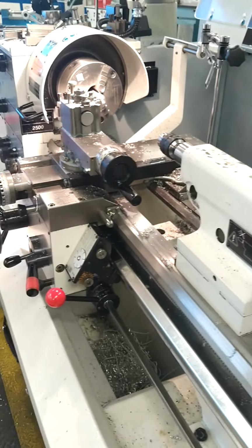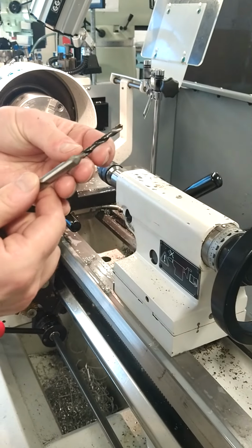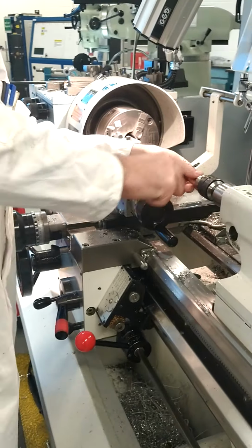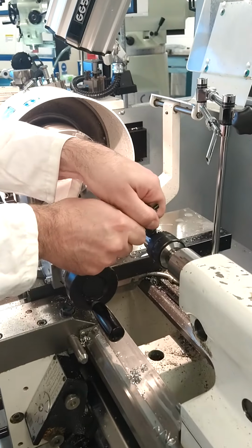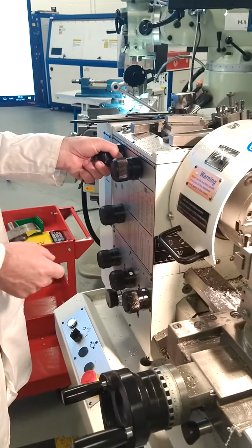And then you can install your center drill bit. It's used first for drilling a pilot hole, before you use your drill bit. The angle of your center drill bit is 120 degrees, and that also matches the angle of your revolving center, 120 degrees, allowing you to support the work in your part. So to use the center drill bit for the first time, you pop it into the chuck and tighten it up. I'm going to increase the speed now to 800 RPM.